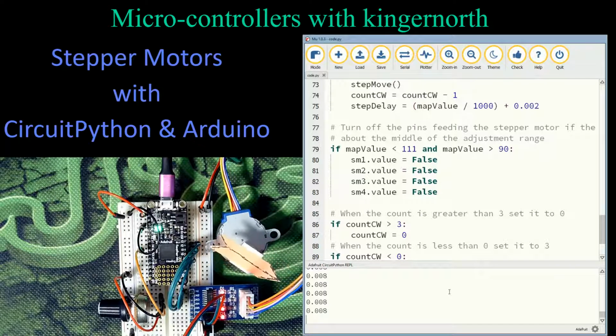You know what? These things are great. You can do all kinds of animation with them. You can do lots of fine control. We've done 3 types of motors now, if you think about it in these lessons. We started out with servos, both continuous and angled servos that only have about 180 degrees of movement. We talked about DC motors, and now we've talked about stepper motors, and they're all a little different from each other. So depending what you want to do, you just decide which motor works best in your application.